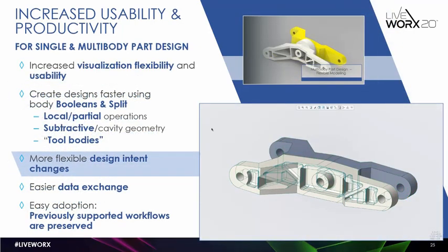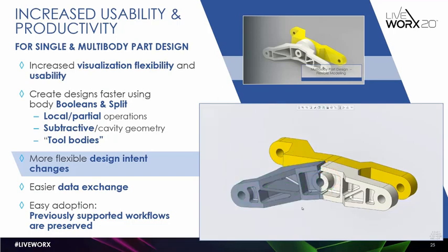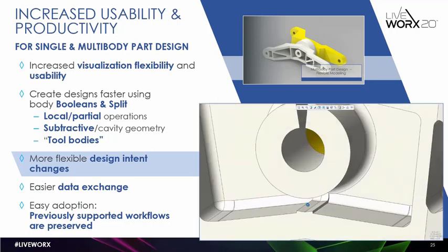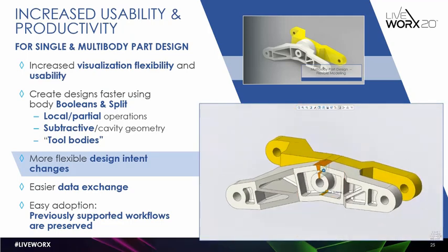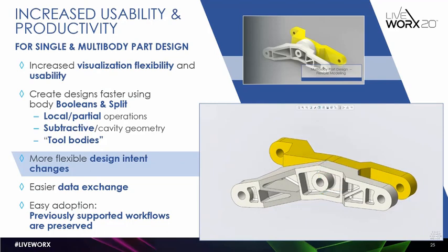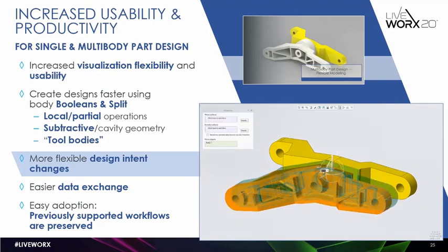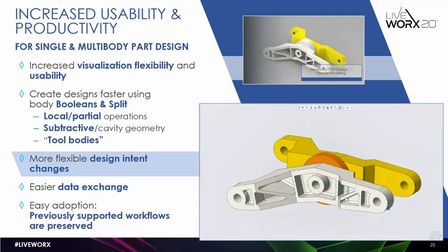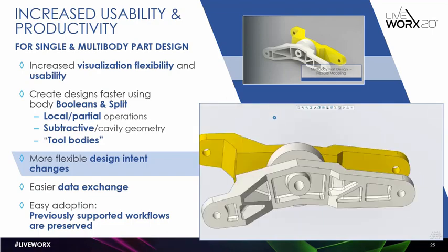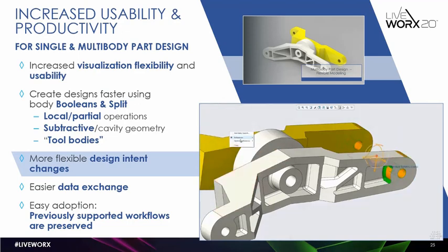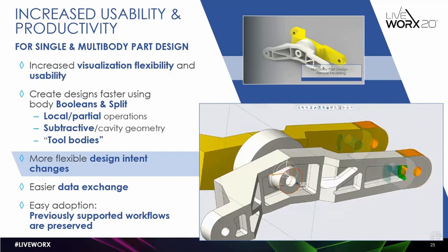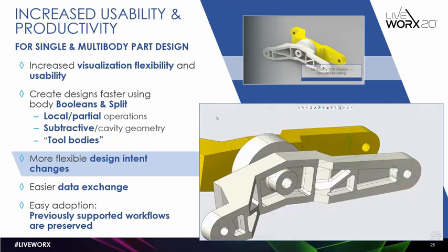Multibody concepts also allow for more flexible design intent changes on native or imported parts, as illustrated here. Splitting the body into several pieces and then leveraging Creo's powerful flexible modeling capabilities on those geometric bodies significantly broadens the flexibility you have to perform dramatic design intent changes quickly and efficiently. Again, you might want to note how the geometric search tool as well as the geometric move operation along with its tangency control behavior can work on geometry of multiple bodies.